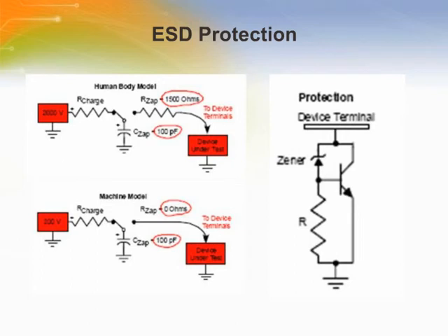ICs typically incorporate some means of protection against electrostatic discharge voltages, or ESD. All device terminals incorporate independent internal protection similar to that shown. Referring to the protection circuit on the right, ESD voltages presented to the device terminal break down the Zener diode. A breakdown of the Zener causes the transistor base voltage to rise, turning on the bipolar NPN transistor, dissipating the otherwise destructive energy to ground.